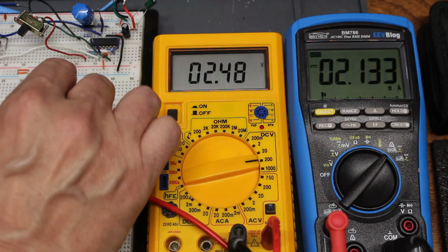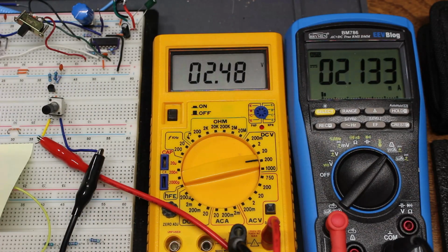It's transitioning to a state called saturation. At that point, the collector to emitter path looks like a small resistor, and our current source becomes little different from a voltage divider. Let me measure a few voltages and currents so that I can graph them.